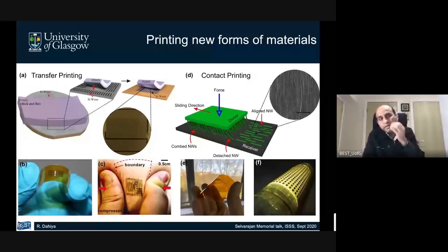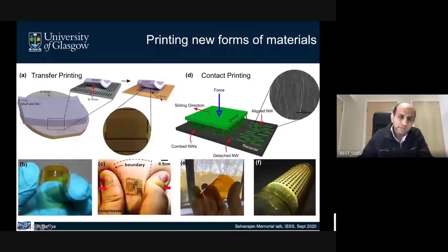The transfer printing approach came from Professor Rogers' group. What it does is you can realize all silicon micro nanostructures on the wafer, with all high temperature processing steps carried out while these structures are still on the wafer. And then you can lift them with PDMS using van der Waals forces. There is good enough adhesion to lift these wires from the wafer. And once they are transferred, you make one more transfer to the final receiver substrate. As an example, in this case, it's polyimide. So once you receive, you have these structures on the receiver substrate.